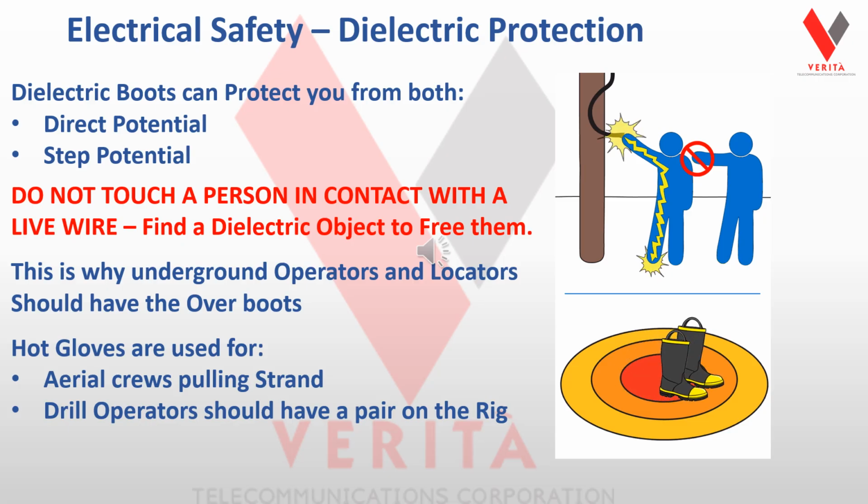Now, if somebody's on a line that's hot, do not touch them. You know, don't do it. Find a dielectric object to free them. Now, this is why underground operators and locators should have overboots. If the drill head strikes a line, it's going to energize that ground right below that person that's locating. Also, it's going to travel down the rod back to the drill itself.